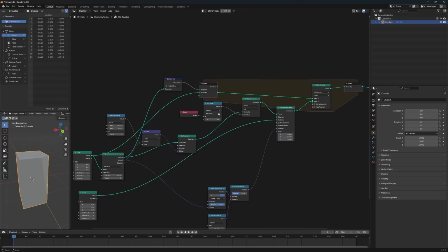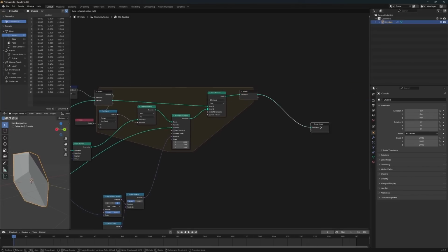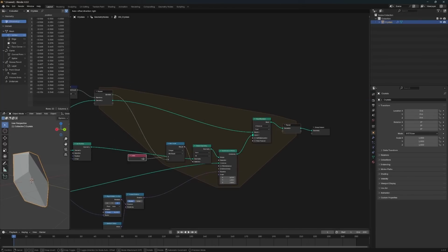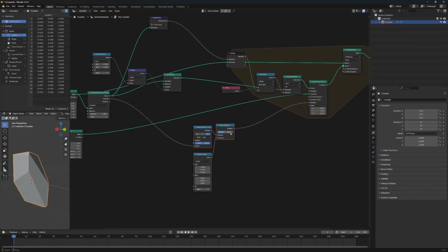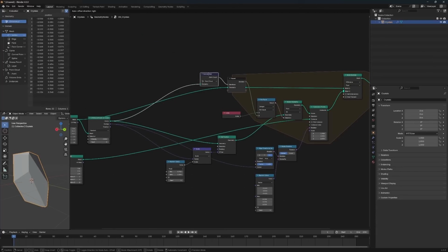Now the loop will cut 31 times the exact same object. So we have to vary the object with each iteration, and that is easy because we have this selection field down there, and we can just use the iteration number to feed it into here. And you see, now the loop happily cuts our cube into a nice crystal shape. Let's clean up a bit. So here we have the selection of the cutter object. Here is the begin of the repeat. Down here we have the rotation of the instances. Here we have the offset, like so. And up here we have the domain size.